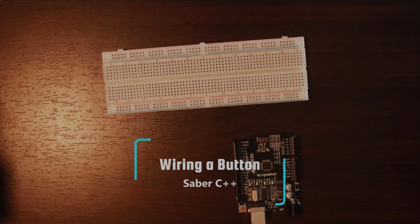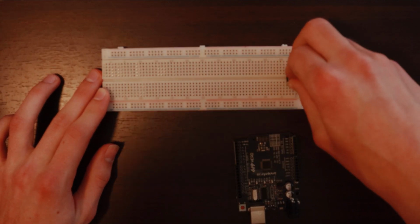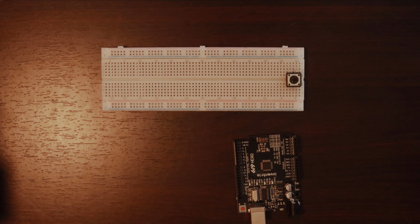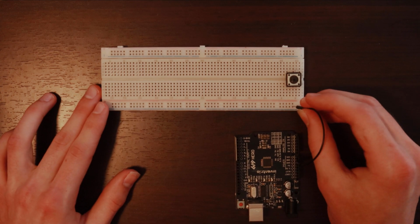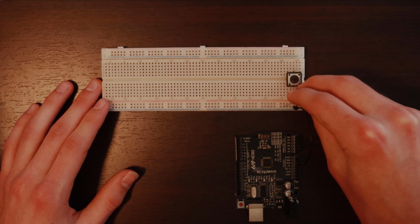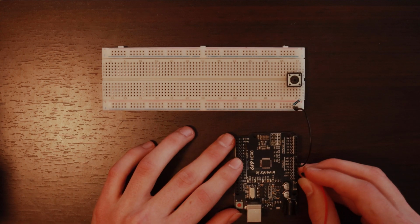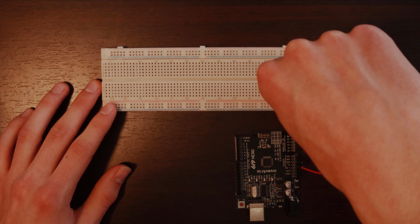Now let's take a look at using buttons with our Arduino board. First, I'm going to put this button on the breadboard, making sure that it spans the gap in the center, so that the leads don't connect to each other. Next, I'll connect a wire from one of the ground pins on the Arduino to the blue line on the breadboard. Next, I'll take a resistor and connect it from the blue line on the breadboard to the right side of the button. Then, I'll take a wire and connect it from the 5-volt pin on the Arduino to the right side of the button.